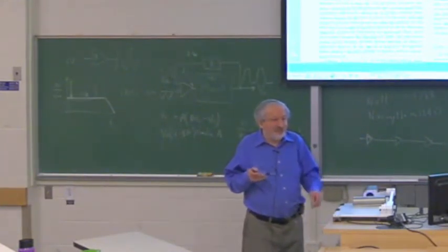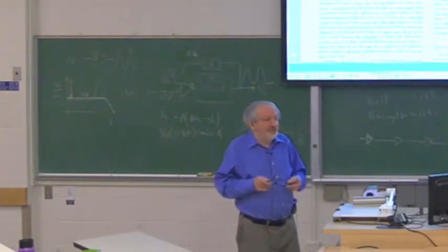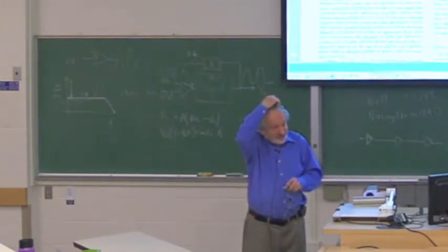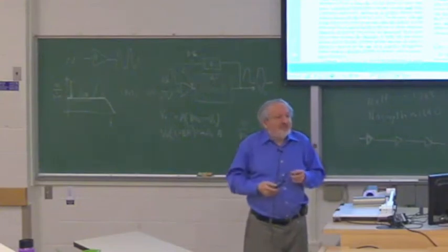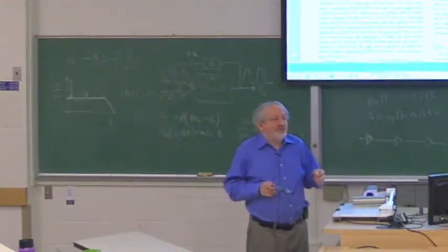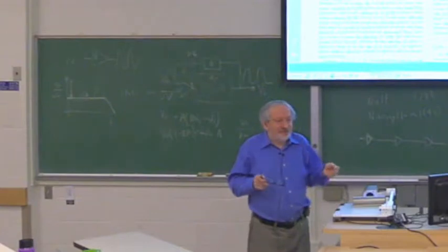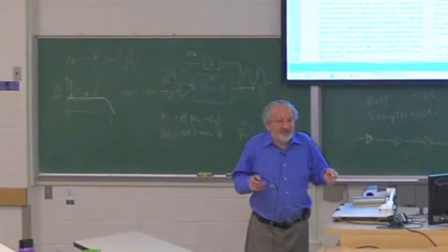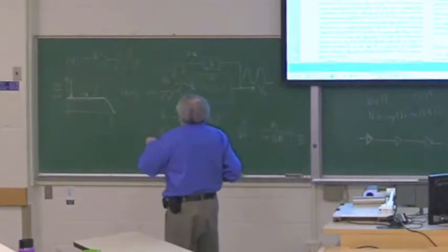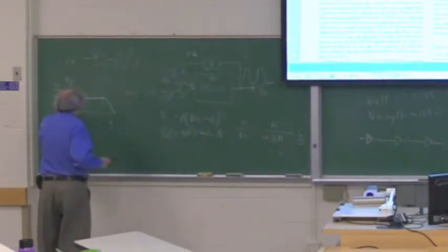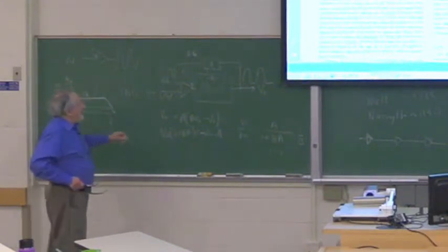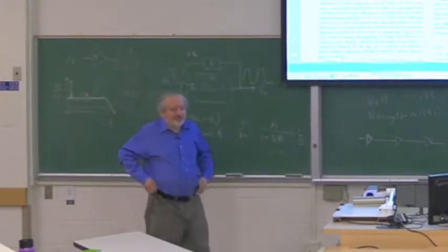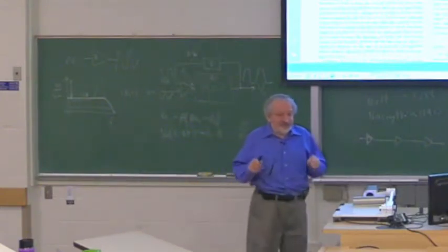If you look at the spec, it says 80 dB, sometimes it's in dB, but you know how to convert, right? So a gain of 10 is 20 dB, and it's a logarithmic unit. Anyway, most op-amps have 120 dB, which is 1 to 1,000,000 voltage gain. But when you use them, you usually need a gain of 10 or 100. So you are only using a small part of it, and you are left with a huge gain inside to fight the errors. Is that clear, that whole thing?